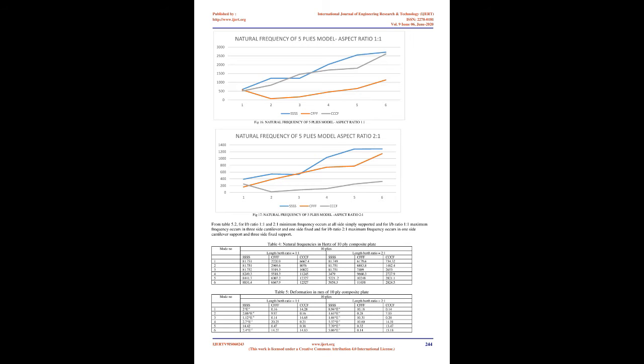The importance of damage detection for composite structures is often emphasized over that of metallic or plastic structures because of their load-bearing requirements. Vibration monitoring data is analyzed to monitor the characteristic changes in rotating machinery caused by imbalance, misalignment, bent shaft, mechanical looseness, faults in gear drives, defects in rolling element bearings and defects in sleeve bearings. Vibration analysis is used to detect early precursors to machine failure, allowing machinery to be repaired or replaced before an expensive failure occurs.